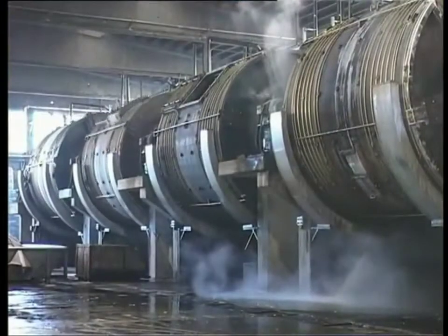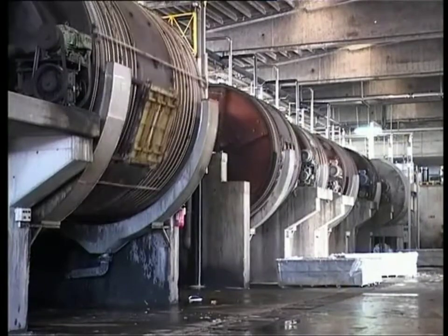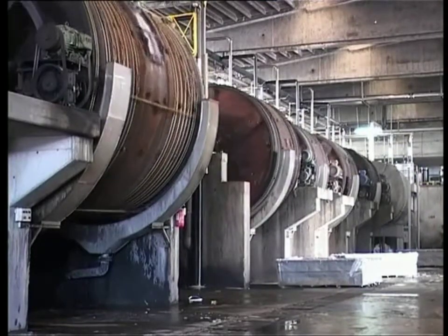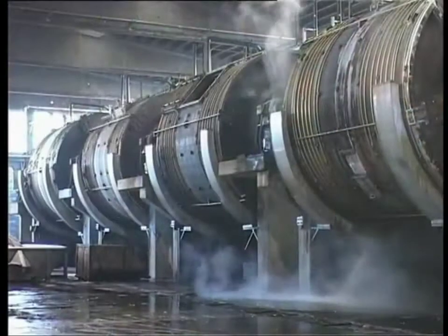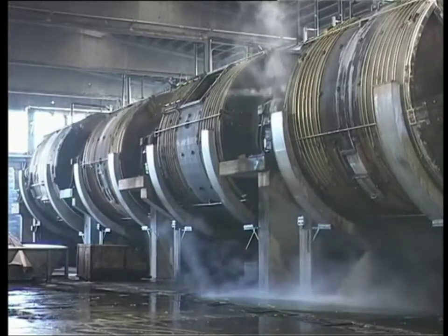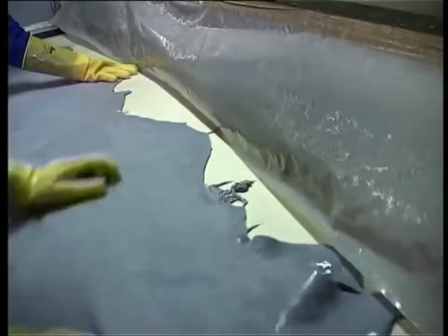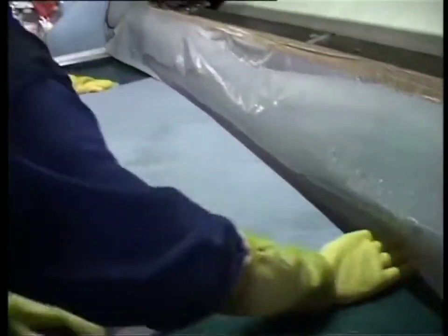Now the tanning process takes place. In this case, the hides are placed inside a wooden rotating drum specially designed for tanning. Tanning agents convert the raw fibers of the hide into a durable product, preserving it, improving its abrasion resistance and heat and flex resistance, able to endure repeated cycles of wetting and drying. Next, two large rolls squeeze out the excess moisture as the hides are fed through a machine. This is termed wringing.